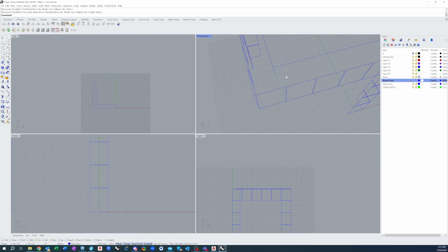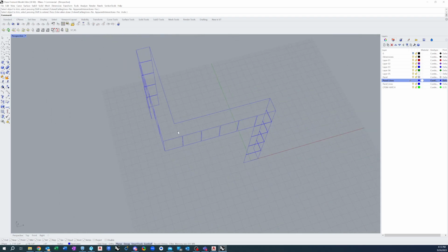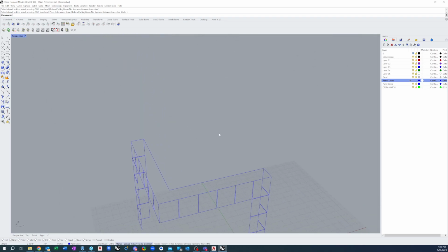And so trim, same as AutoCAD. TR, select cutting object. It's this one. Right click, object to trim. This guy, enter, and I'm done. Right click for enter, and I'm done. Okay, so that's all in.